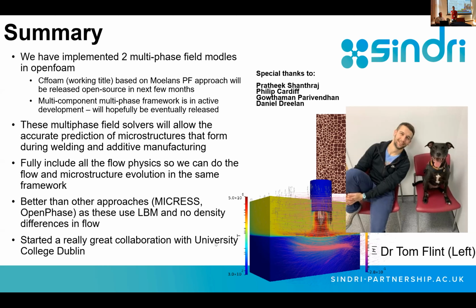Typically it's of the order of a few millimeters, just because we have to have all phase field variables defined in all of the mesh. It really does limit us. The maximum I've ever simulated is, I think, 2 millimeters cubed. That's actually where the cellular automata methods come into their own, because you can simulate huge domains with those, as they're not as computationally expensive.